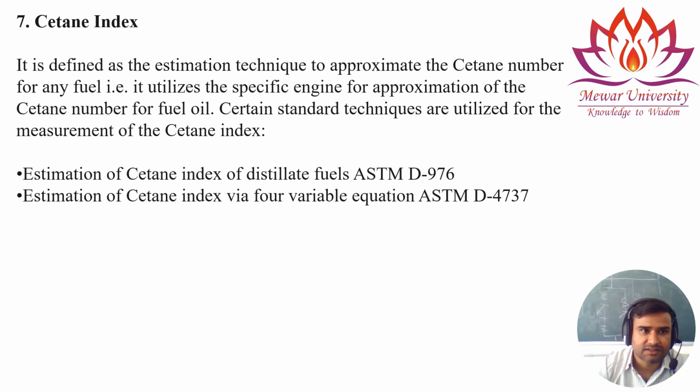Now another characteristic is the cetane index. The cetane index is basically a technique to measure your cetane number. You can see the definition: the cetane index is defined as an estimation technique to approximate the cetane number for any fuel.